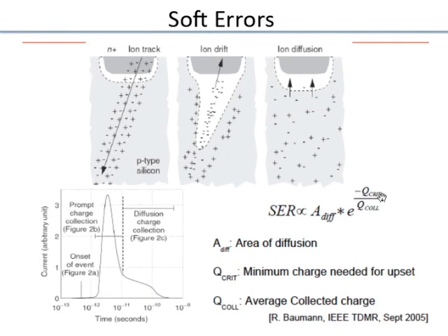And there is also critical charge, which will cause the node to trip and change state. I'll not go into the details of Q collected, but basically there's a notion of a critical charge. If that amount of charge gets created, then the node will flip.